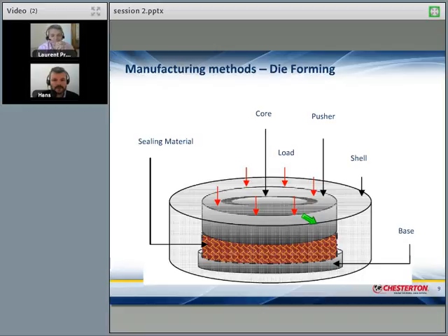This whole process becomes easier when you use die formed rings because they have a higher density, so some of the pre-compression that you would do in the equipment itself, like the pump or the valve, is already done in the factory. Okay. It actually saves time.